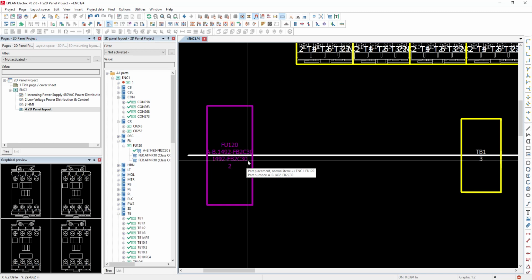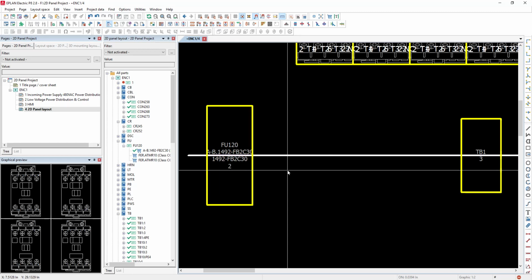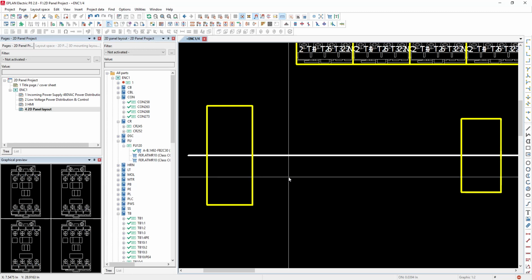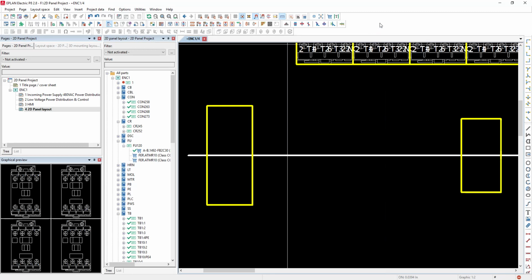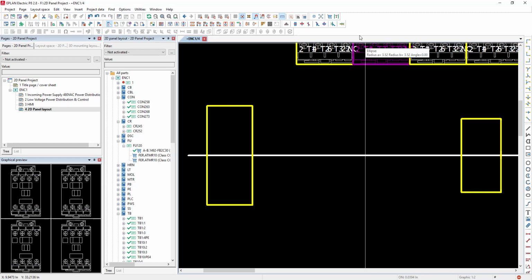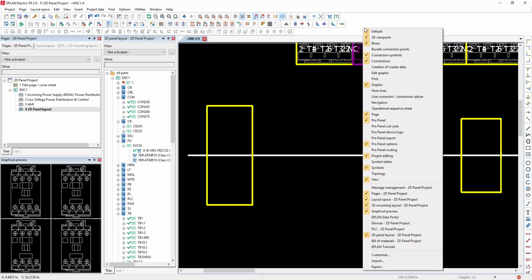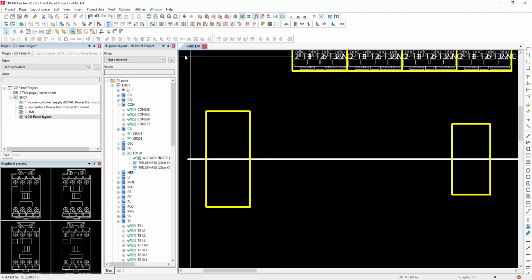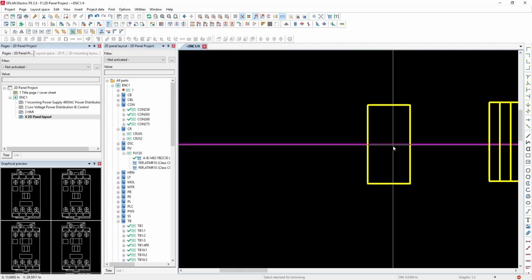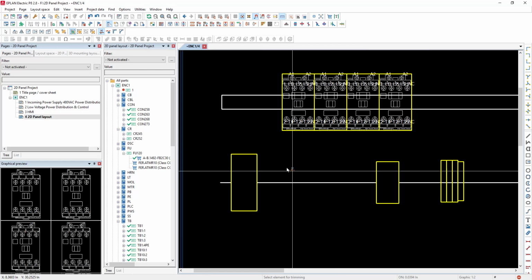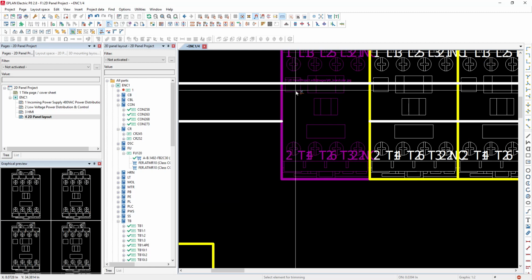There'll still be a little bit of lines that you might have to trim. So unfortunately, unlike generating model views, if you will, in a pro panel environment, you still have to do some lines or some editing. There's a little bit of work involved here. So I can use my edit tool line, and maybe I can use here my cut trim, and I can cut that line off and cut that line off again to make it a little bit more clean.